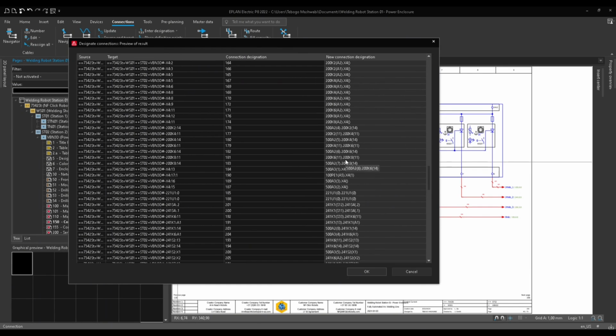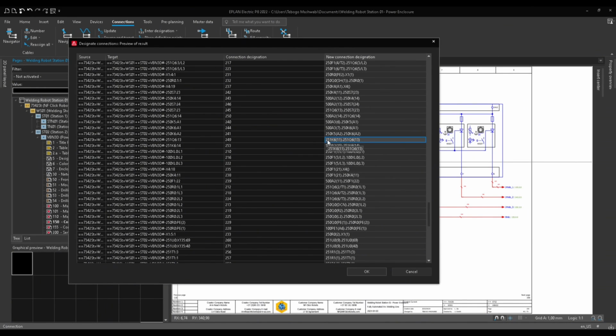So if I make an example, let's see, maybe I'll look at one that is a good example to look at. So you can see this one. It says it comes from this DT. So it's a relay, which is on page 251. It's on K6, so it's on column 6. And you can see it comes from number 11. So it comes from the connection point number 11 of that contactor or that relay, and then it's going, so we're separating it by that dot.